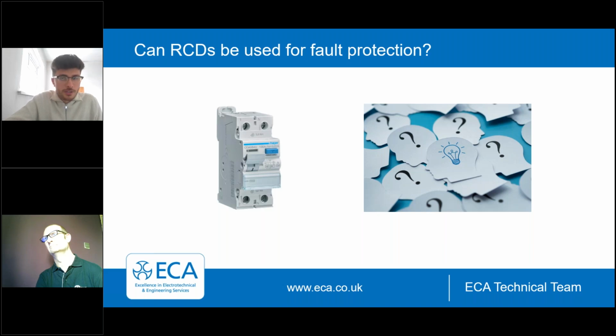But there can be other circumstances. A designer may elect to use an RCD as their method of fault protection. Due to the constraints of the circuit, they may be struggling to achieve the required impedance value. It may be very low. So an RCD can be used for fault protection. Designers can opt to do that.